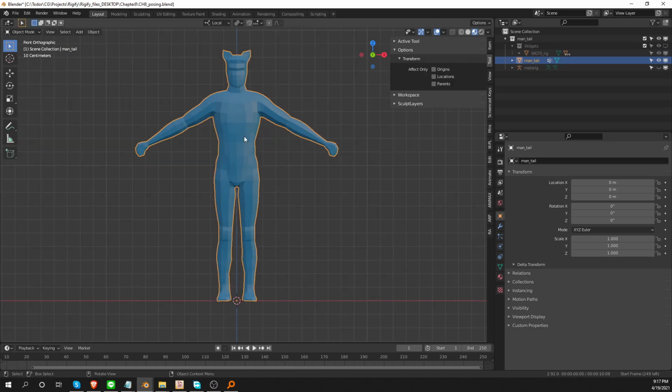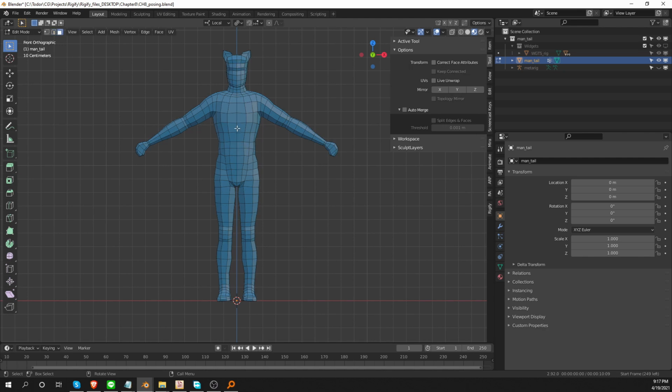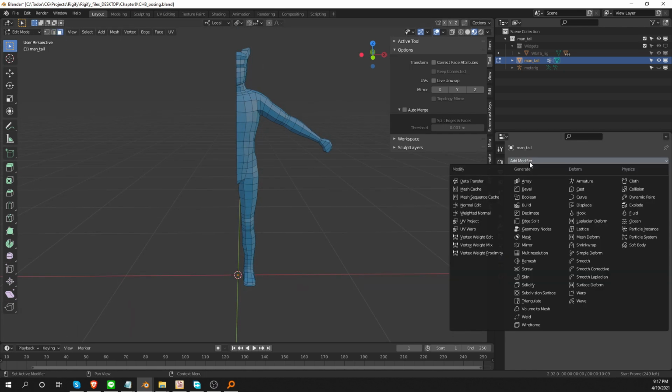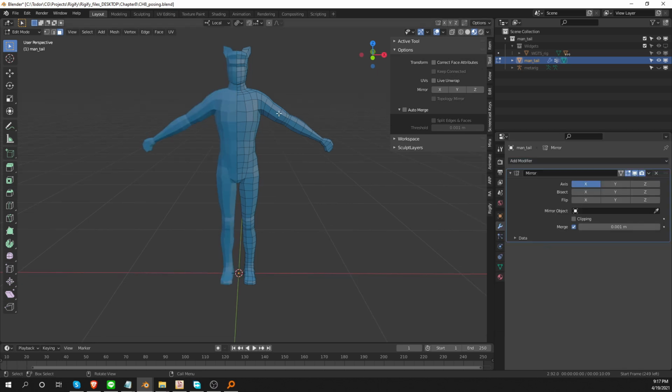And of course, there is the mirror modifier. If I only have half of my mesh and I apply a mirror modifier, I will create a non-destructive symmetry. This modifier also has options for mirroring on X, Y, and Z. So most symmetry tools in Blender can work on any axis, but the weight paint tools for bone weights only work on the x-axis. And for that reason, when working on symmetrical characters that will be rigged, you should have them face forward.